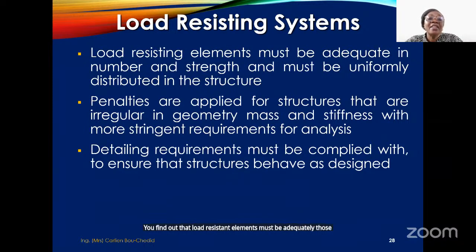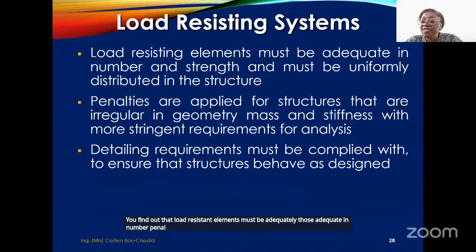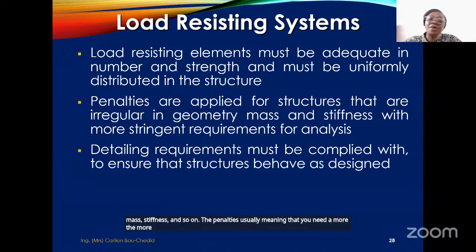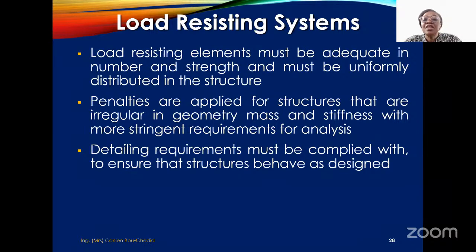You will find out that load-resistant elements must be adequate in number. Penalties will be applied for structures that are irregular in geometry, mass, stiffness, and so on. The penalties usually meaning that you need a more stringent analysis of the structure.